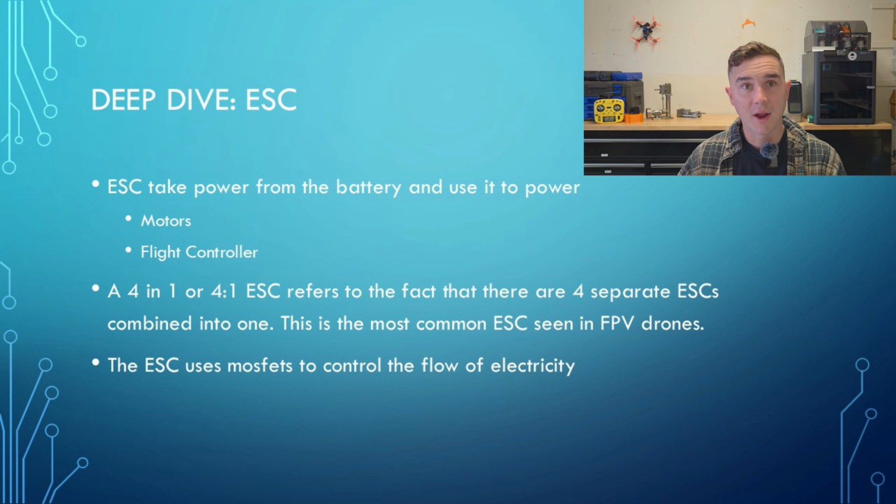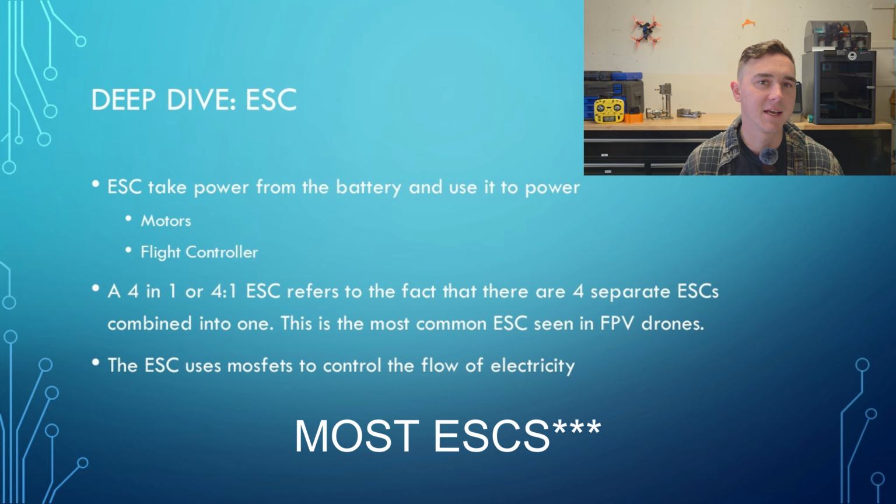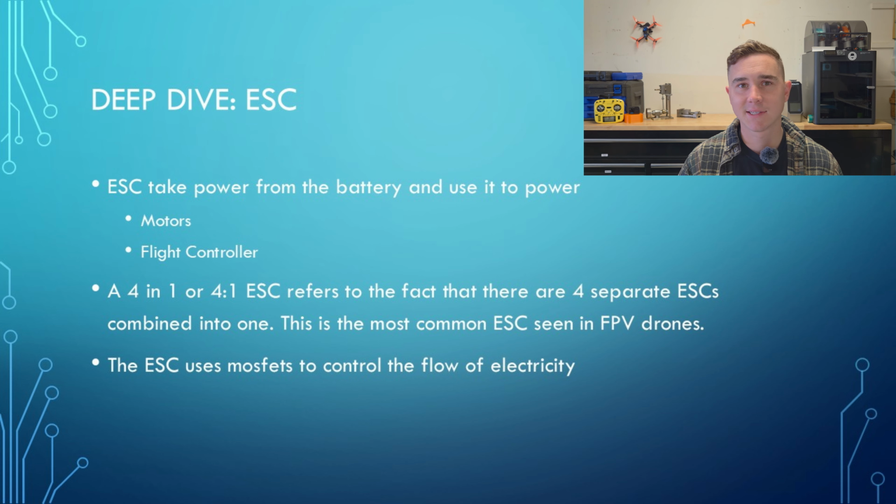Right now, most flight controllers that you're going to get are called 4-in-1. What that means is there are 4 separate ESCs within that one little package.